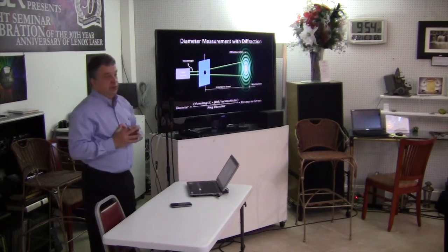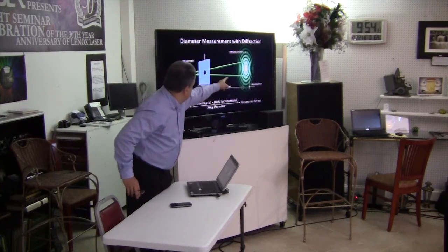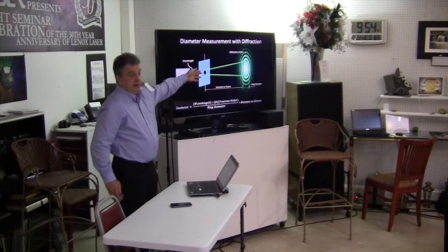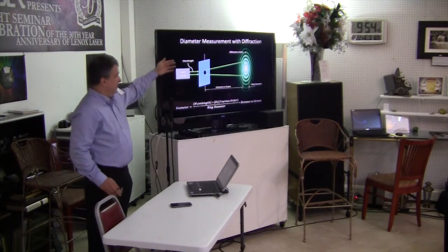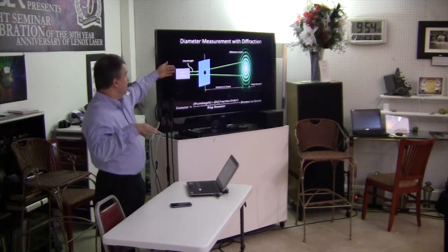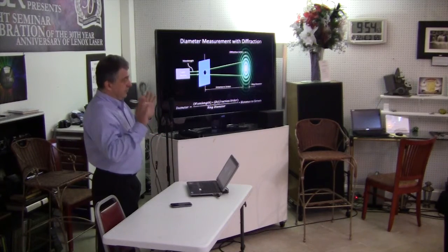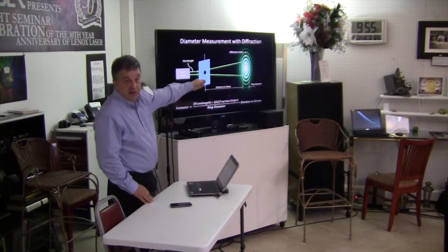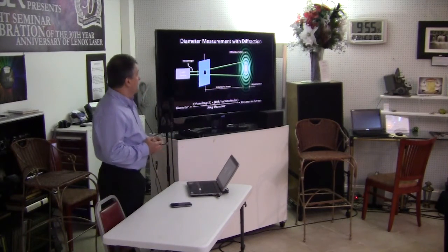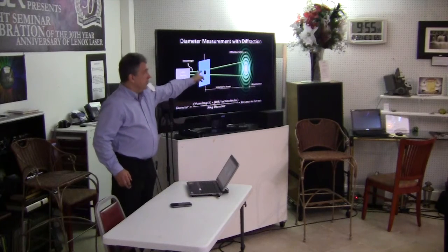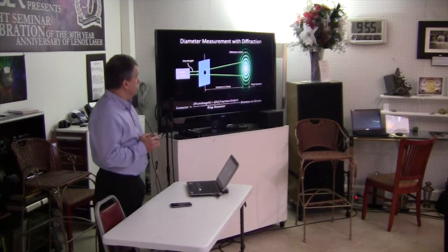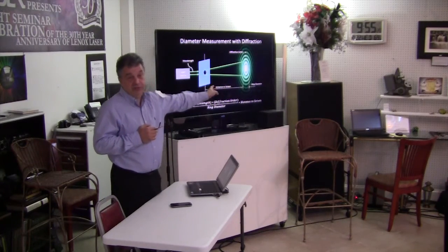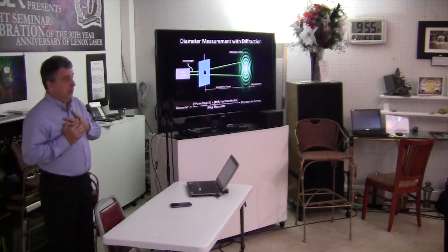The end user is using those particular products to generate a diffraction pattern. If you take the hole and shine coherent light through it, coherent light means it has a few properties: the wavelengths do not deviate, and all phases move together. If you shine the laser beam through that and project it on a screen, you'll see an interference pattern. Depending on the quality of the edges, roundness and sharpness of the edges, you'll have a certain contrast of those rings. This is what the industry is looking for.